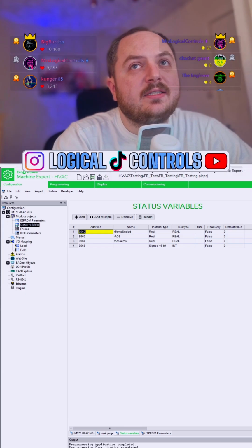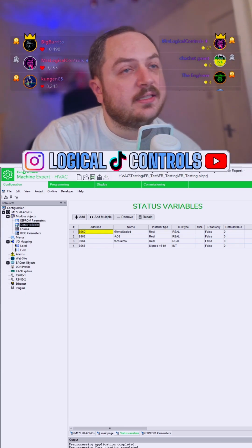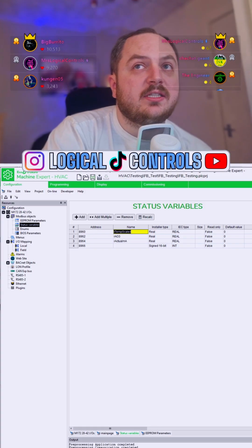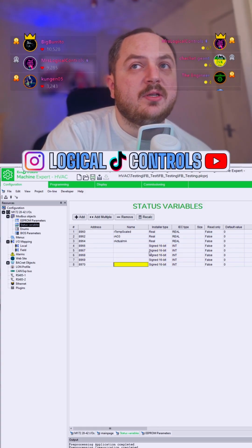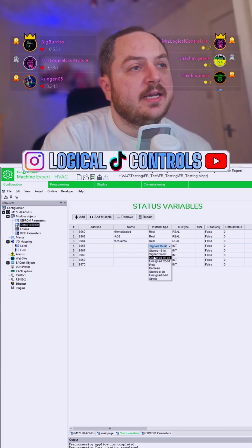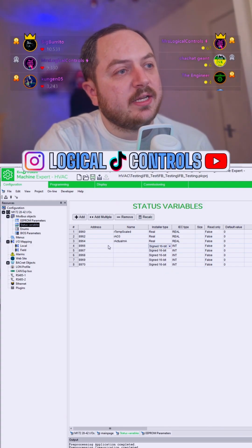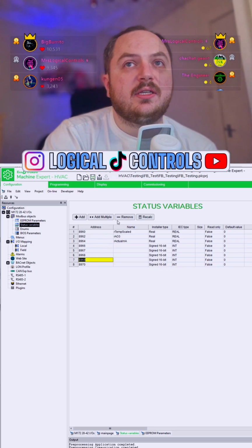So 8960. If I read on function code 3, made the offset 8960, I would be able to read the scaled temp value. And just by adding parameters and changing what the data type is, it just adds them already to the Modbus registers. So yeah, Schneider make it super easy.